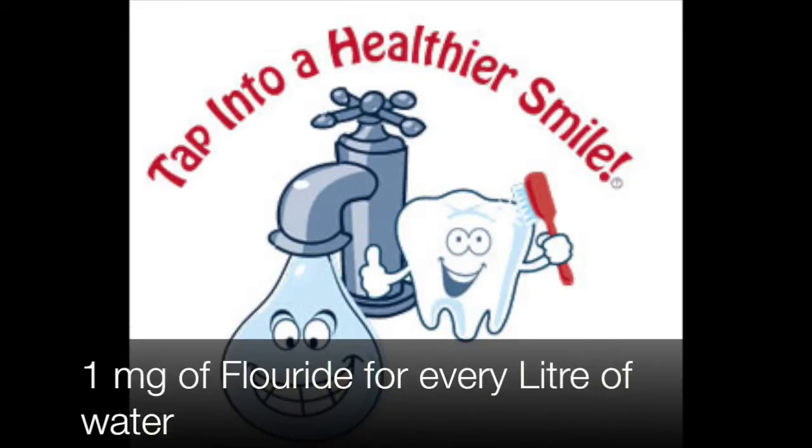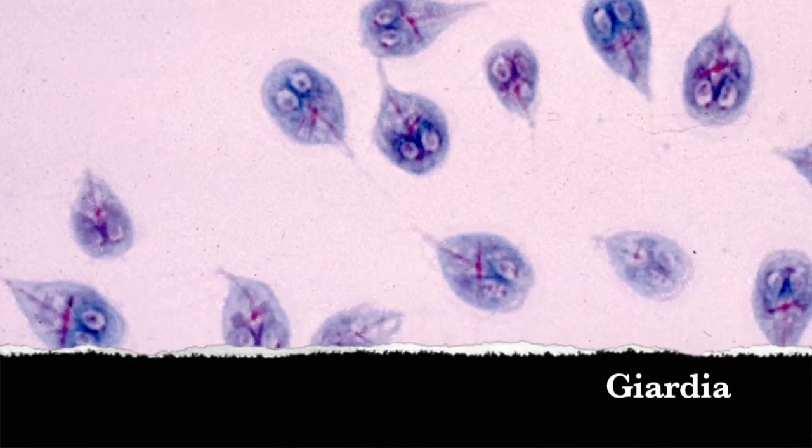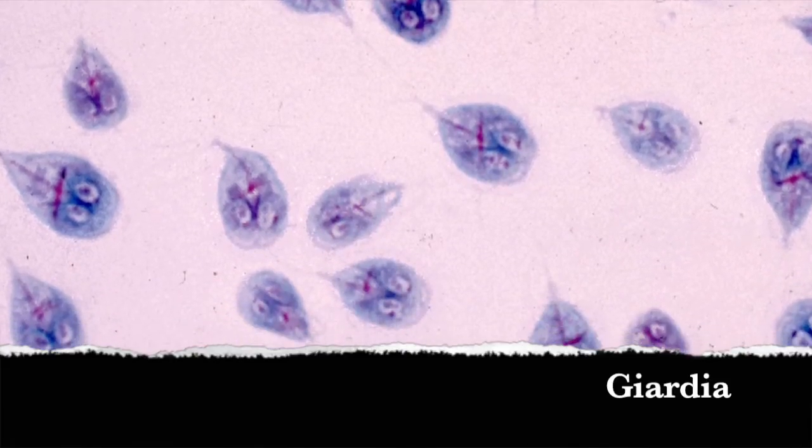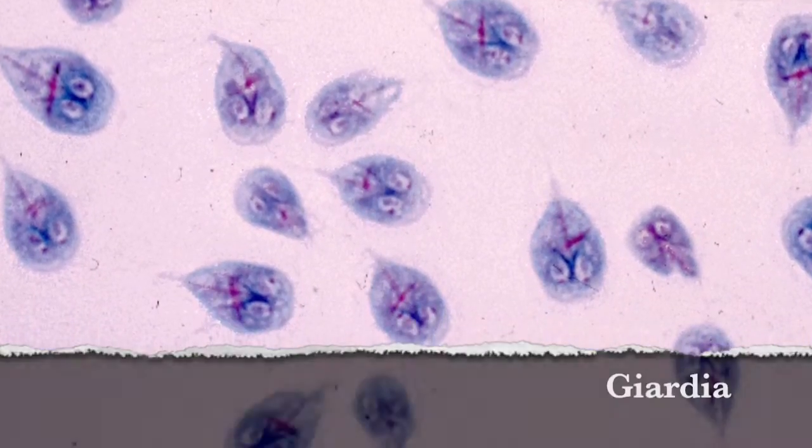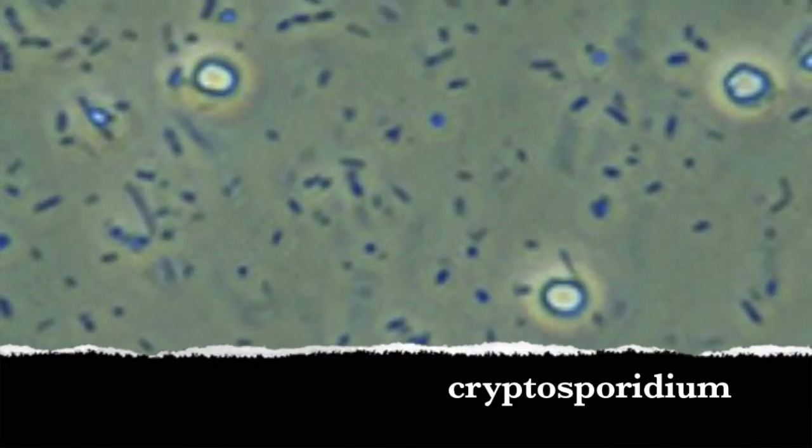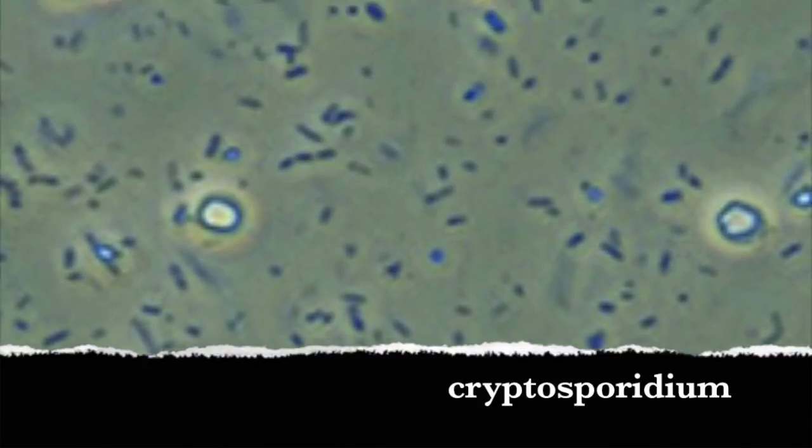Fluoridation. Fluoride is added to the water under the direction of the New South Wales Health, Fluoridation and Public Water Supplies Act 1957 to help prevent tooth decay. Drinking water must contain 1 milligram of fluoride in each litre of water. The testing and monitoring of Sydney Water is very effective as there is rarely any waterborne disease outbreak. They keep their treatment plants so effective by testing the water 6 days a week. On these days, they test for Giardia and Cryptosporidium 3 times that day.